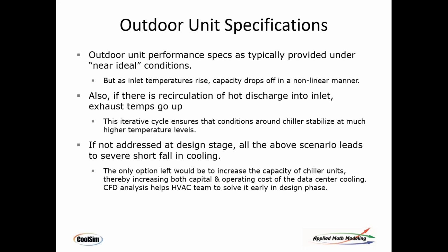I've had many customers say to me, I can't keep my data center cool on a hot day, and I don't know why. It's unusual because I certainly have enough capacity, because I bought this many tons of cooling. Well, guess what? It's not a constant. The tons of cooling, or BTUs, or kilowatts, however you want to measure it, actually declines as inlet temperatures go up, and it does so in a nonlinear fashion. And if there's any recirculation going on, where it's coming out the hot side and going back into the cold side in a loop, short circuiting, then this makes it even worse.